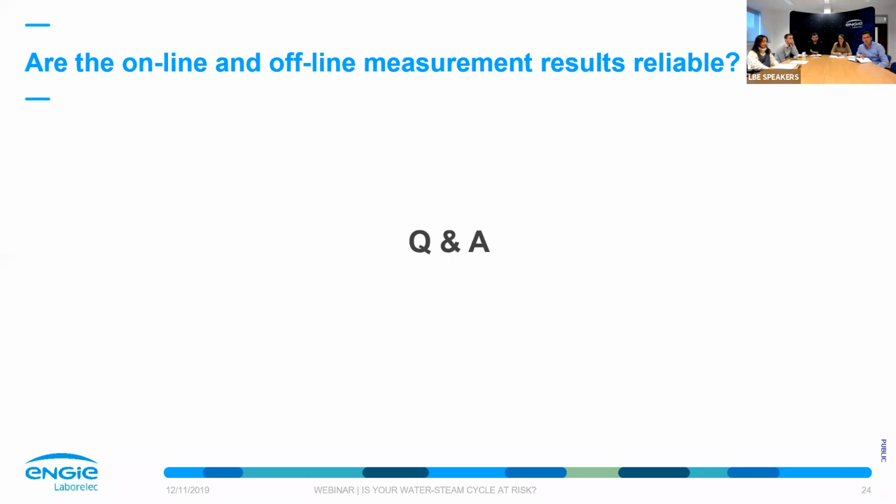Next question is, because of very high purity water, it requires specific pH measurement. What is your recommendation of the type of pH measurements? Yes, for pH measurements, we recommend to use a separated glass electrode and reference electrode. So we don't like very much the combined electrode systems. You also need a high flow through of potassium chloride through your reference electrode.